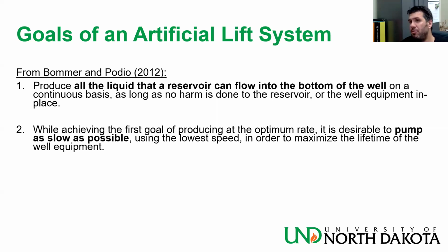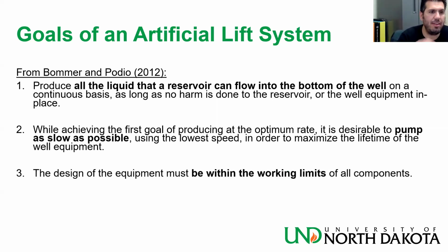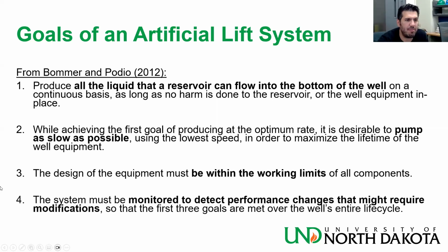In fact, there are many problems, and we are going to see one later today, maybe, one scenario where slowing the pump actually solves a problem. The design of the equipment must be within the working limits of all components, and the system must be monitored to detect performance changes that might require modifications such that the first three goals are met over the well's entire life cycle. So these are the four axioms of what artificial lift systems are helping us achieve.